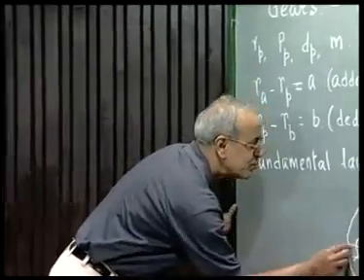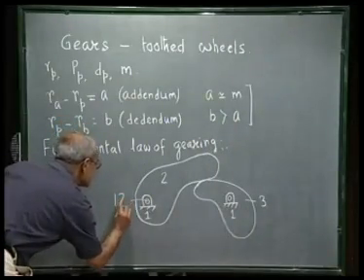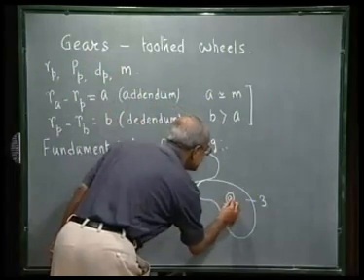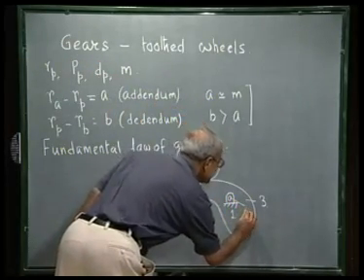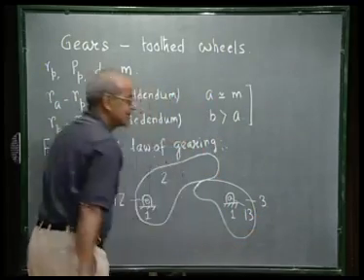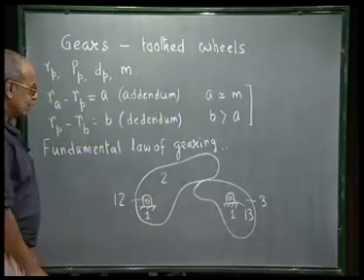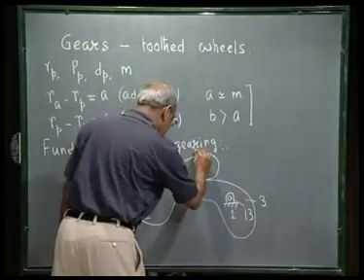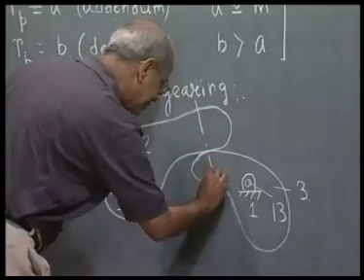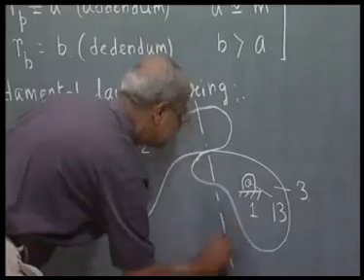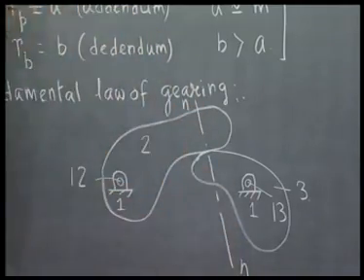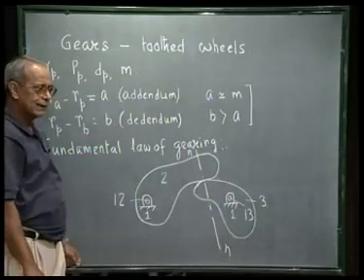So, this revolute pair obviously is the relative instantaneous center 1, 2, and this is the relative instantaneous center 1, 3. Now, the question is where is 2, 3? 2, 3 we do not know where, but definitely lies on this common normal. If I draw this common normal, then 2, 3 lies on this line n n.